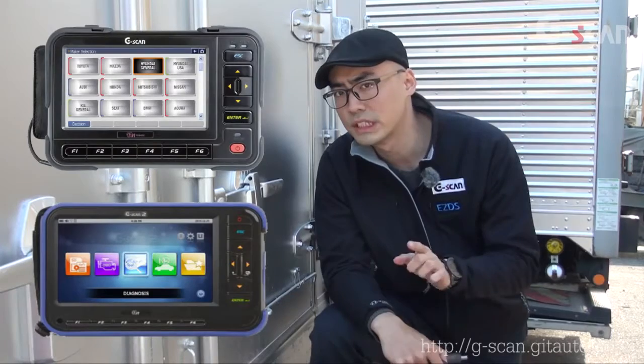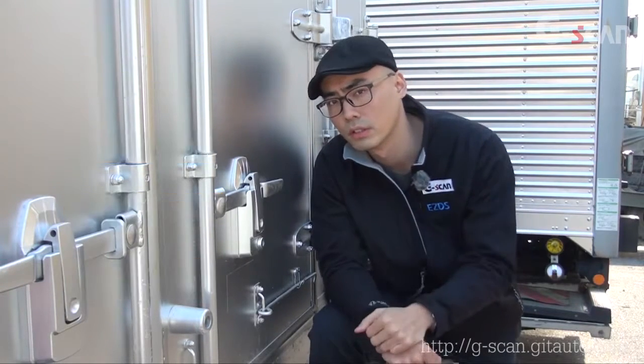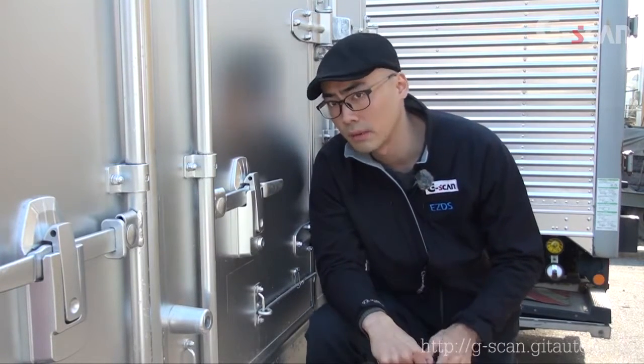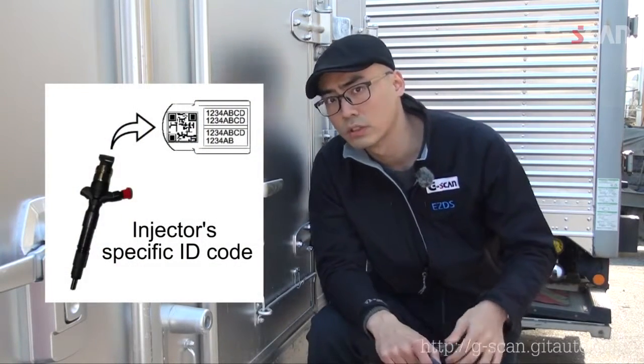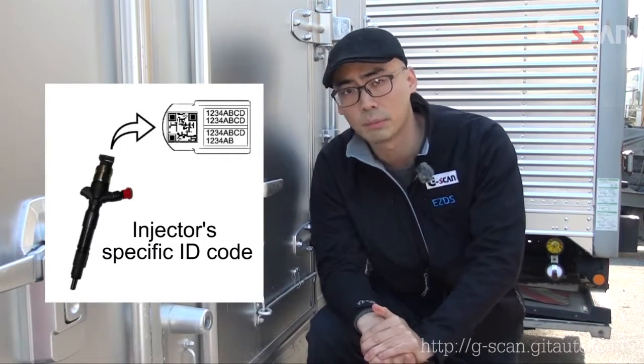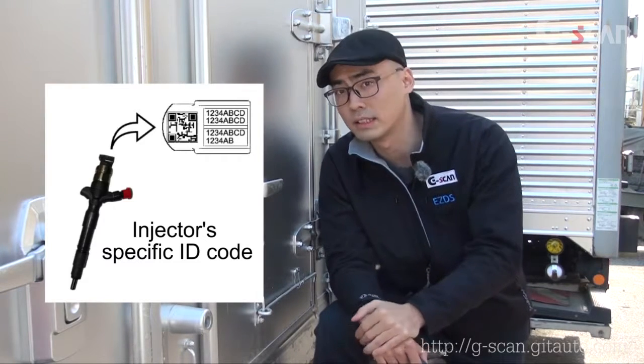Whenever you perform repairs on most recent systems, even a simple replacement of sensors, you must use a scan tool to reset or erase learned data in the ECU. Other than erasing and learning functions, there are calibration, initialization, reset, and coding functions. One out of many different examples would be injectors. When you replace injectors, you have to code or write the specific injector's ID code into the ECU for correct fuel quantity adjustment.